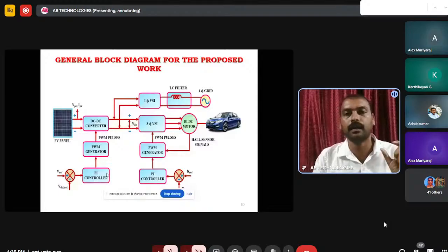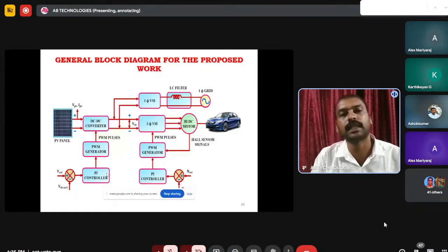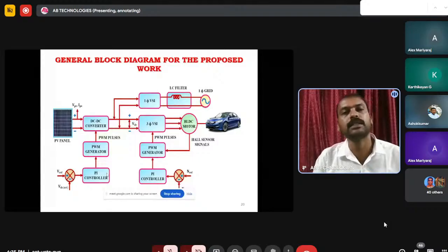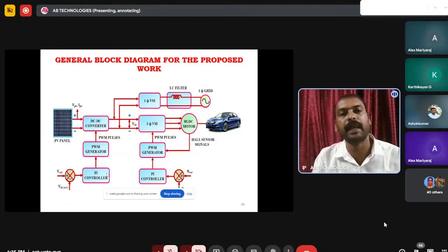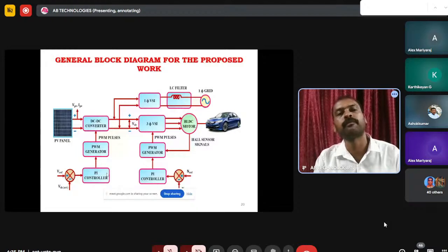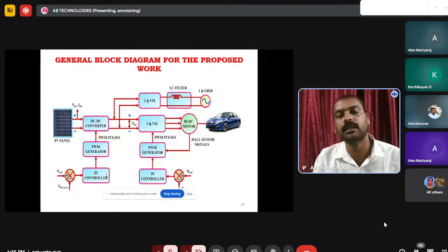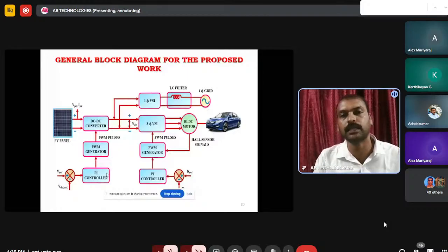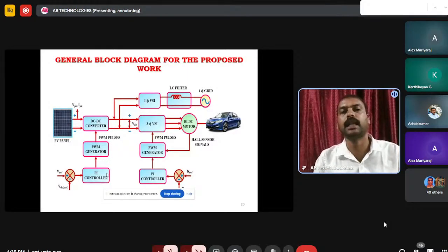That's why we are in need of a DC to DC converter. First, let us take one boost converter. We know the circuit of the boost converter consists of one inductor, one capacitor, one diode and one switch. That inductor and capacitor will store the energy. At the same time, it will reduce the ripple content from the input because that is an LC filter, a single order low pass filter. It can reduce the ripple content in the PV panel output voltage.